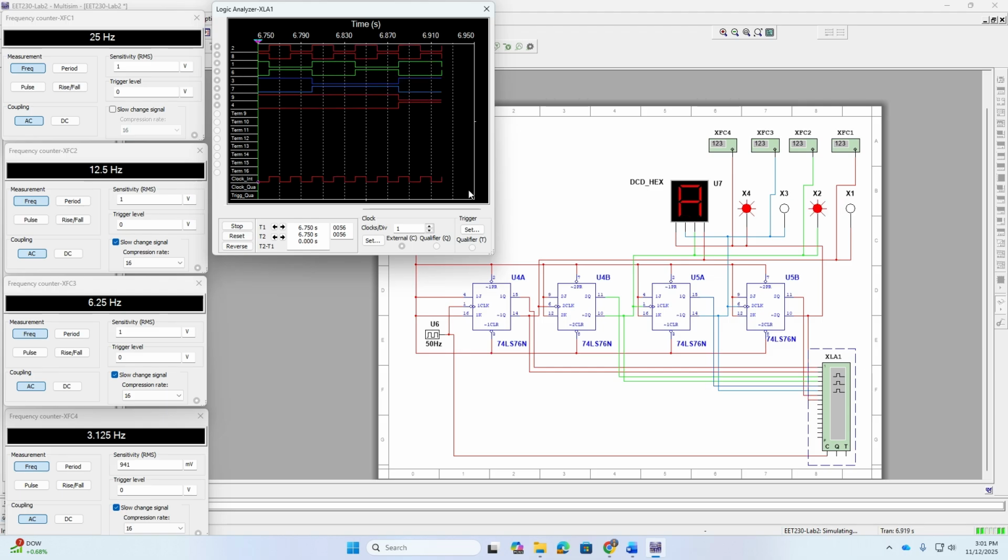What they're going to ask you to do in the lab is, I have this set up for the first configuration of the circuit. What they're going to ask you to do is not use the output of the Q naught to run the clock of the next circuit. It's going to ask you to run the Q into the input of the clock of the second circuit. So all you're doing is changing Q naught to Q to go to the input of the clock. So in other words, get rid of that clock connection there to Q naught and then connect it to Q and do the same thing. Again, the image is in the handout, so you can do that in the handout.